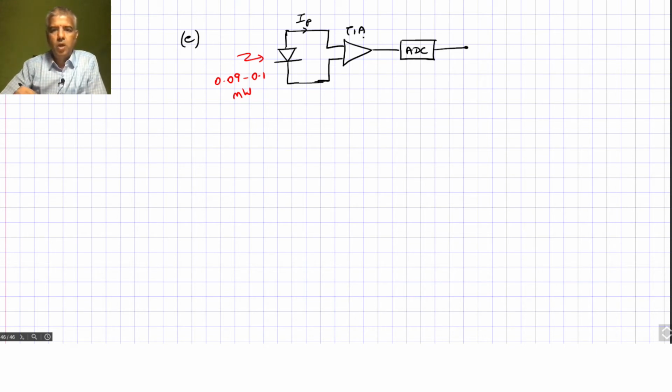Now the question is, what sort of transimpedance gain you need, and then what is the corresponding noise that you accumulate at the receiver. To do that, we need to understand that this ADC is given as 0 to 1 volt. So, with the maximum power that you have here, it should be such that it's filling the ADC. Okay, so that's what we want to first find out. You need to have a transimpedance gain such that...